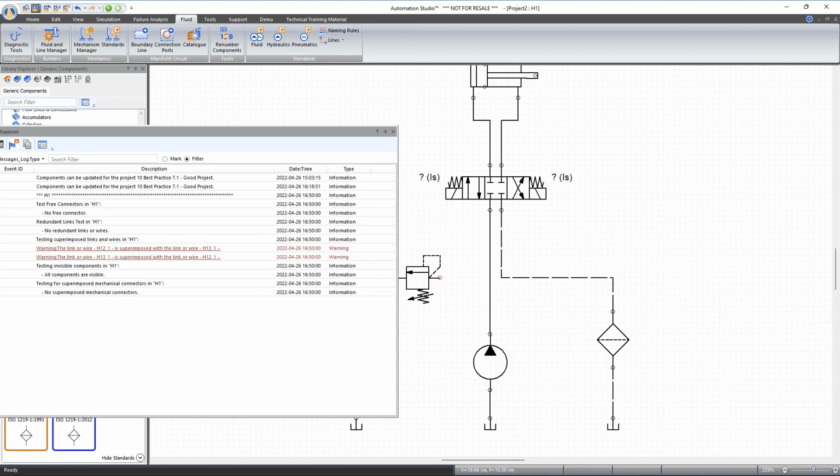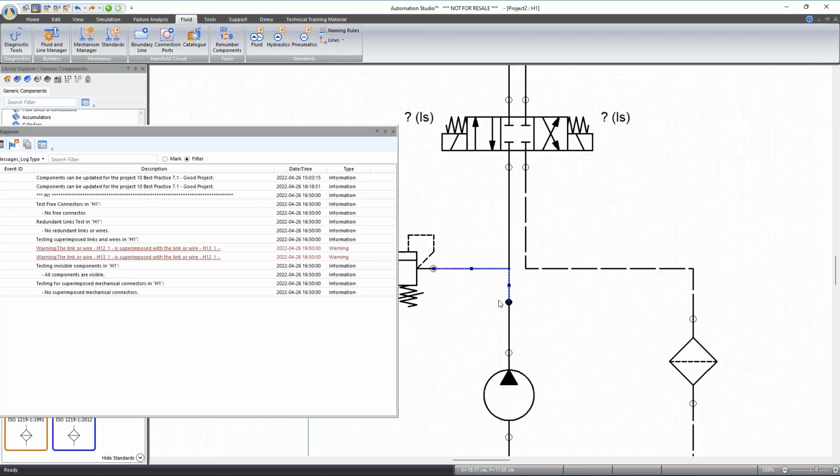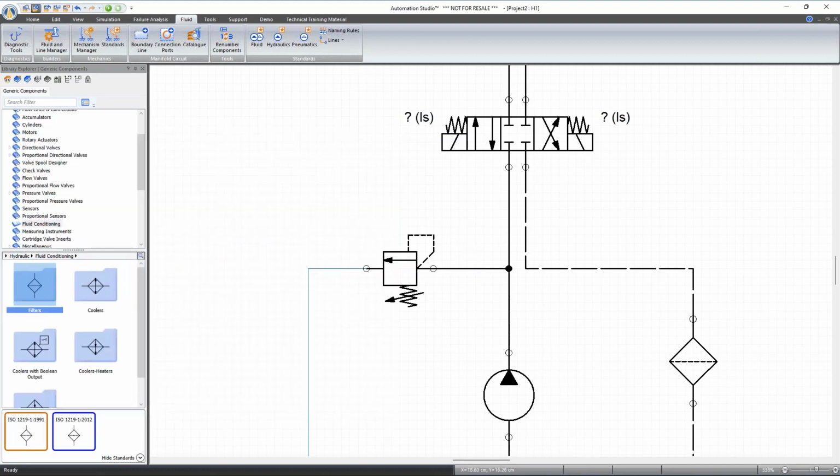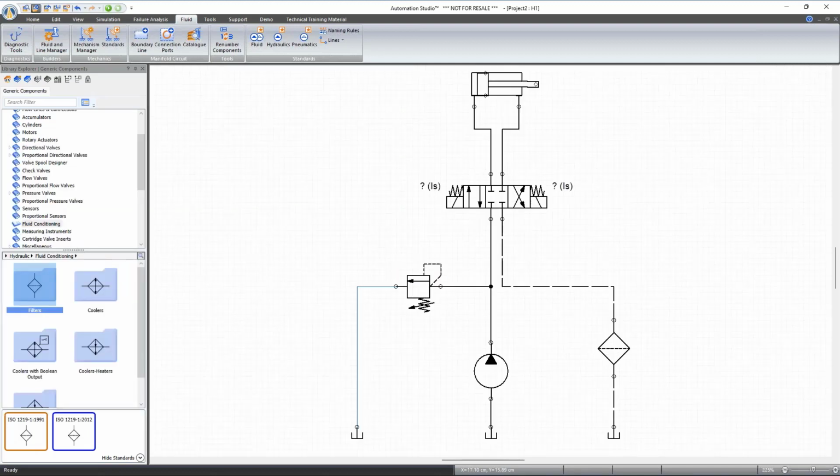We also suggest not erasing any lines, especially when your project is almost done, because you may have given some identification, some information, some sizing to those lines. It's always better to move the lines from the grips here, to resize the line or to change its layout. Like that, the line will only change its layout, and will not change any internal properties that you have given.